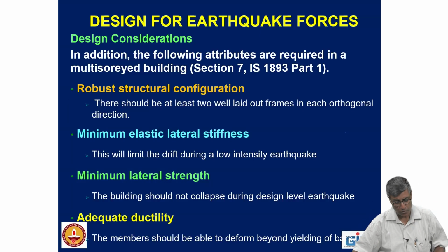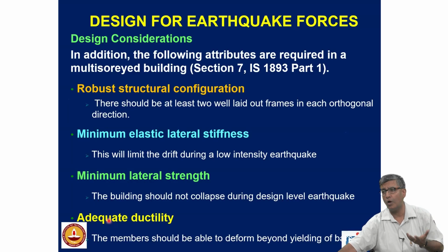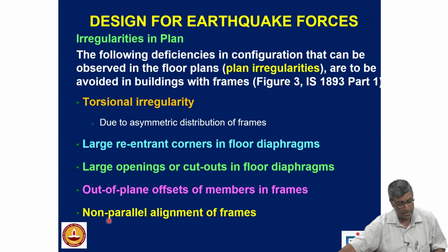And the last one is the adequate ductility. This is where most of the research goes, that how I can make, which is concrete, which is inherently brittle, how can I make it ductile? Okay. With reinforcement, both steel, these days also we are having fiber reinforced concrete.